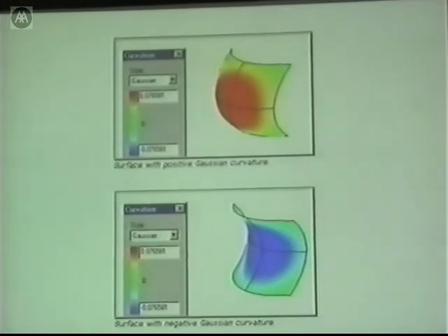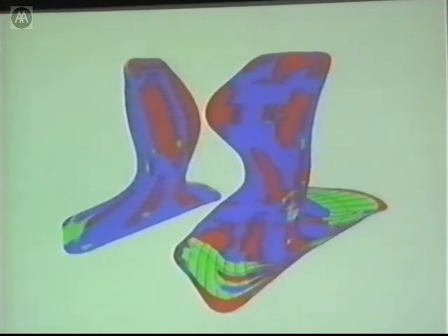as red. Negative Gaussian curvature or anticlastic curvature is saddle-shaped, like the lower image, and in the following images color-coded as blue. So here you have the two volumes analyzed regarding Gaussian curvature respectively. And what is important here is that Gaussian curvature analysis serves, among other purposes, to determine whether a surface is developable or not. What that basically means is whether it can be unrolled and produced from a flat plane or not. In a sense, once you do such an analysis, you can go two ways.